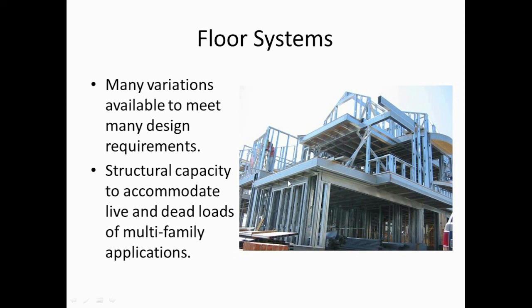If you look here, we have a cantilever here, we have a cantilever there, we have a cantilever here, we have this big box section coming out to pick up a cantilever which will be here. Huge punched opening here. Look at that long span header. I'm assuming that's at least a 2-car garage, and notice how the header is supported by jamb studs directly underneath it. This really and truly to me points to the flexibility in design that can be accomplished when using cold-formed steel framing.